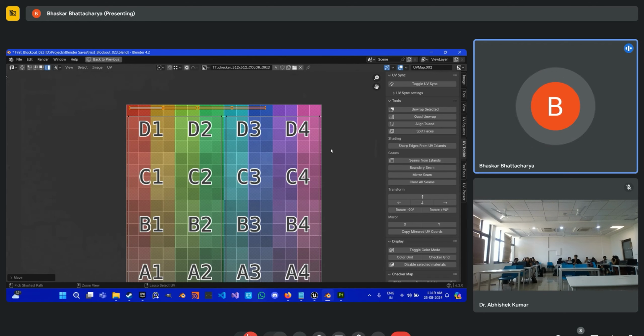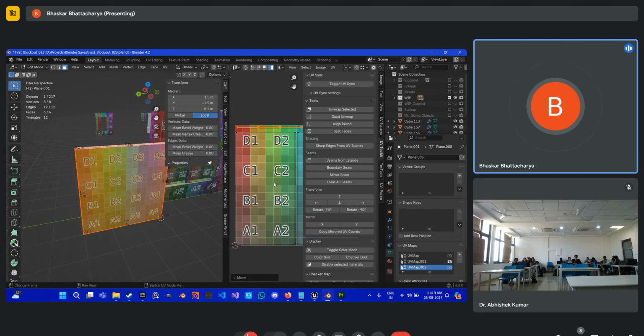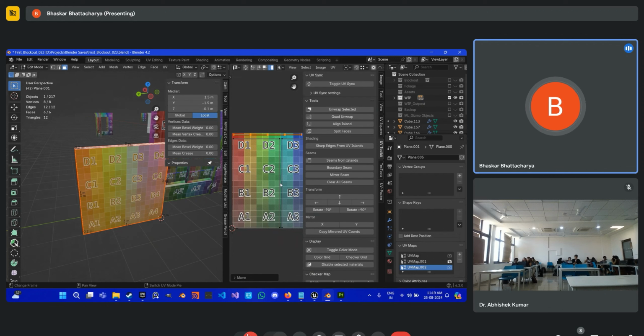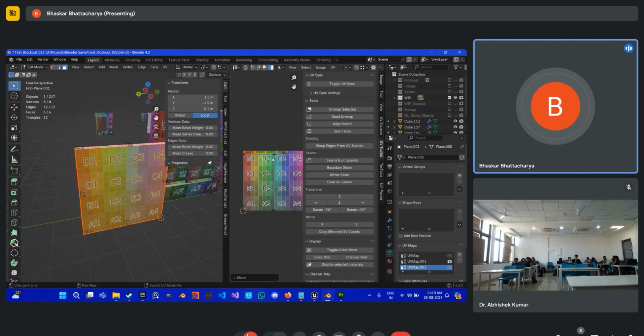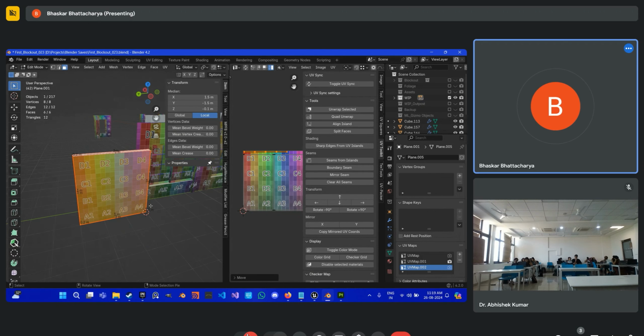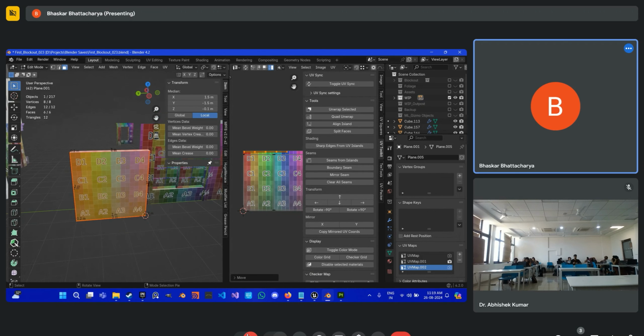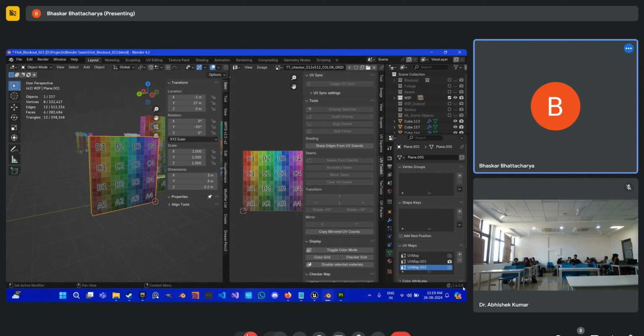It is because light map UVs are usually extremely small in resolution, like 256 by 256. So we need to make sure that the faces which are very important are occupying the most UV space. So these are the three UV channels that we usually keep.